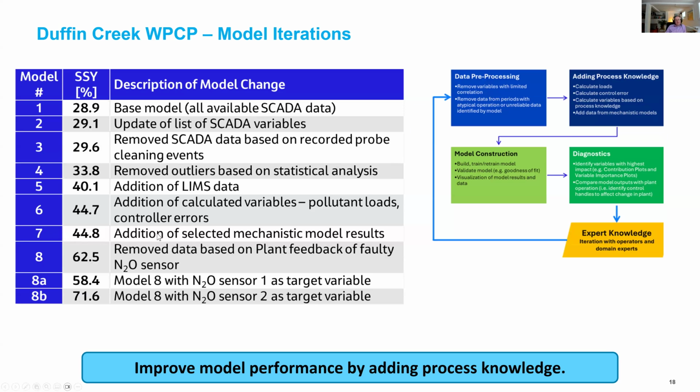One additional thing, that's model 7. We decided we had a roughly calibrated model, right? We are looking into aeration, and we know the model was not calibrated in detail. But the thought process was that we mainly want the dynamics. The first step in data-driven models is that you normalize and mean center the data. So whether you hit that ammonia peak exactly or not is of no importance to the model. So we thought if we add some more ammonia and nitrite information, or information on the dynamics, that may make a difference, right?